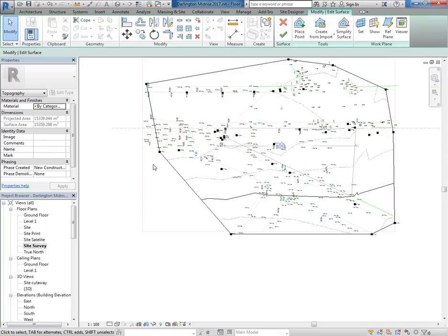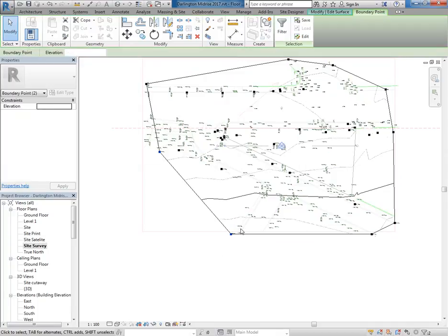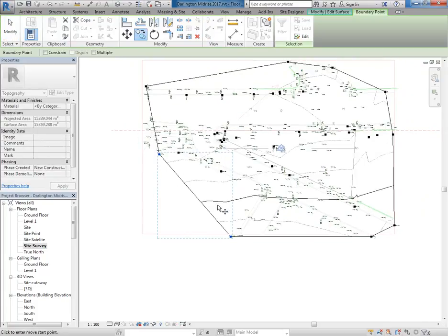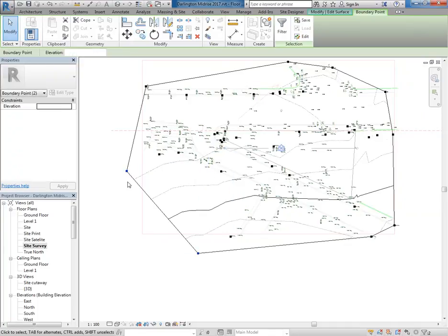And what I was just going to quickly show you then as well is that you can extend your surface using a really simple trick, and that is to copy the points. And so remember, you're not going to be building on this area over here, so it doesn't need to be perfectly accurate, but you want that to show quite often in some of your drawings, some of your views. So it's not a problem to copy those out as long as you follow the contours. Once you've got enough points to get a good general idea of the shape of those contour lines, then you can copy the points out and try and just keep that general direction for the contours.